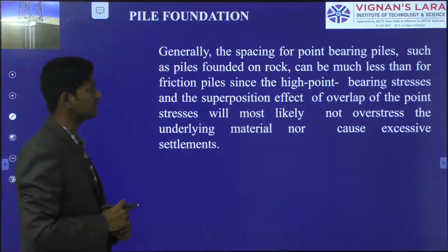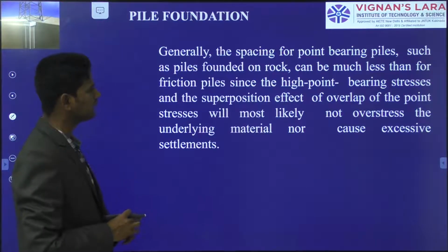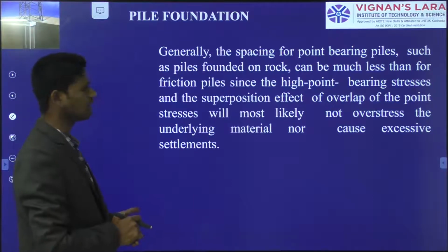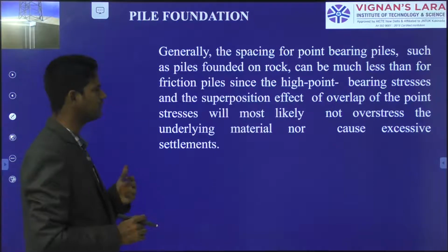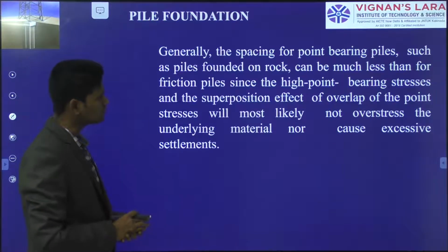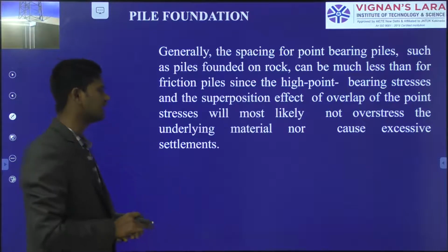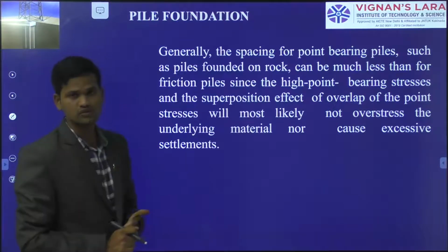Generally, the spacing for point bearing piles such as piles founded on rock can be much less than for friction piles, since the high point bearing stresses and superposition effect of overlapping of the point stress will most likely not overstress the underlying material nor cause excessive settlement.